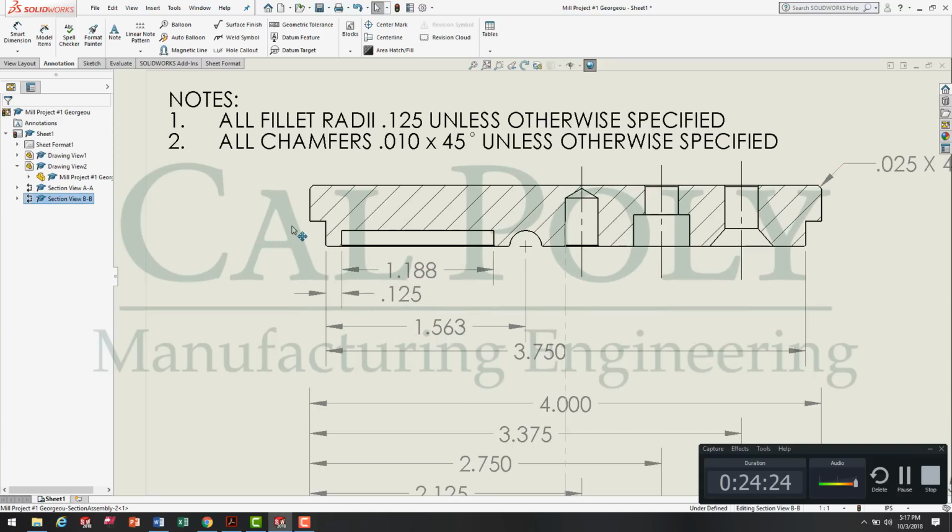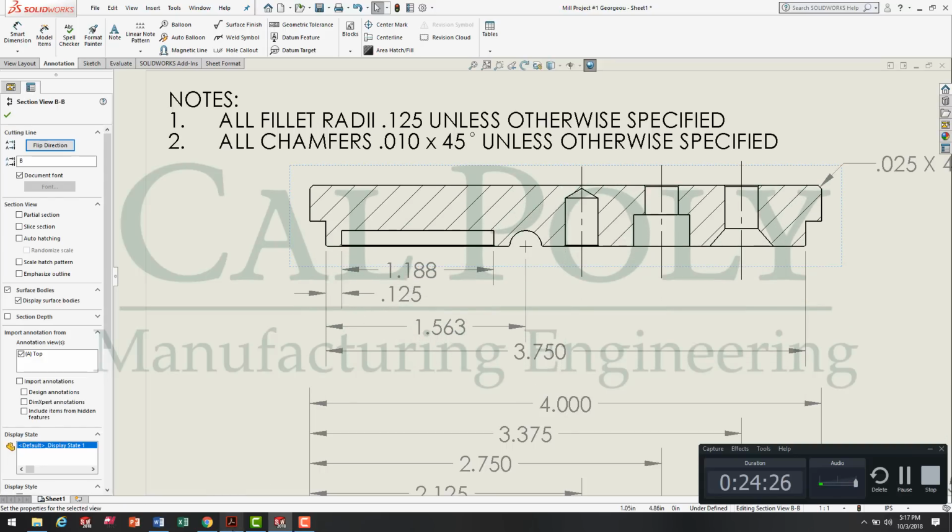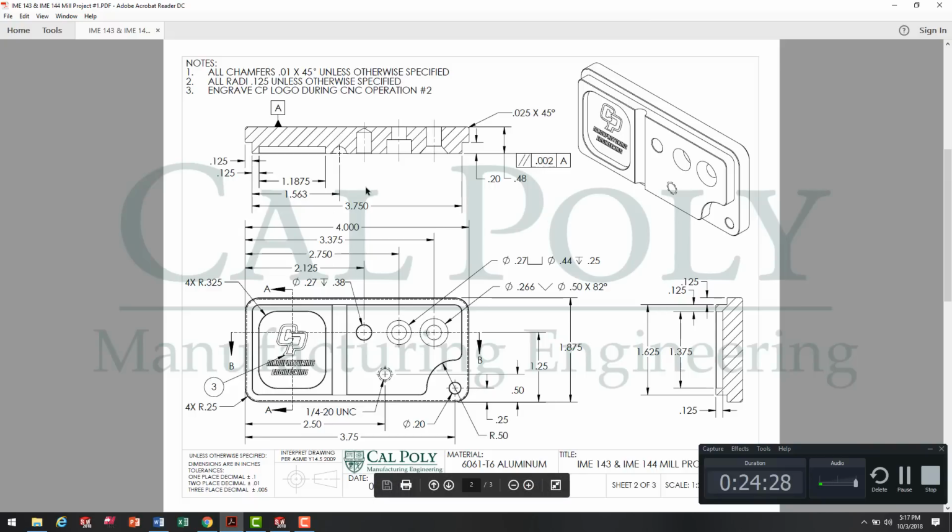And we'll move that upwards and we'll go back to our drawing. So looking at the part, you'll see we've got the 1/8 inch selected, the 1.1875 dimension selected. We're just missing this 1/8 inch dimension, and then 2 depths. So we'll move back to our model.